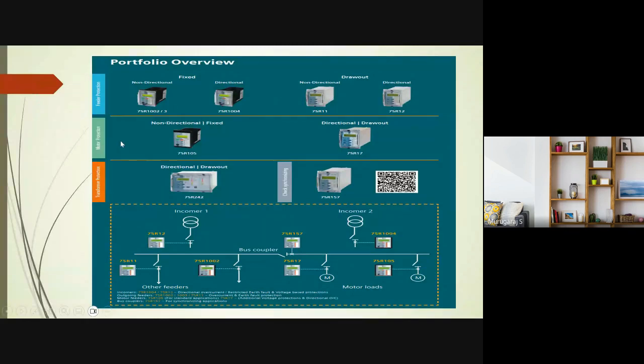And in motor protection, there are numerical relays available for protecting the motor. Generally, these numerical relays are used for motors of 90 kilowatts and above in the market. There are also transformer protection relays available in the market, which are obviously directional, voltage based. A transformer basically steps up or steps down voltage, and there are check synchronizing relays.